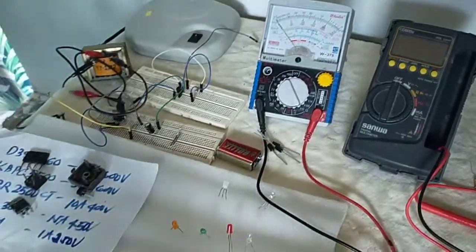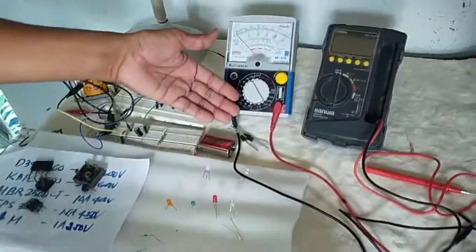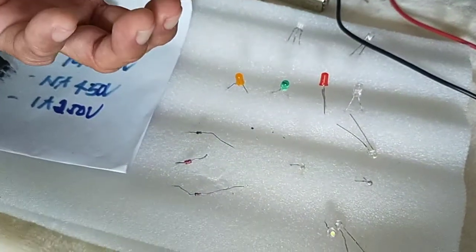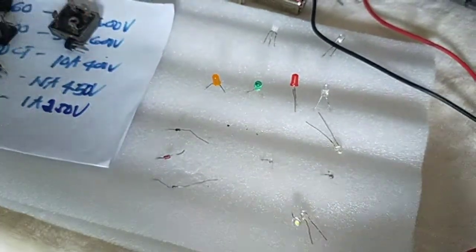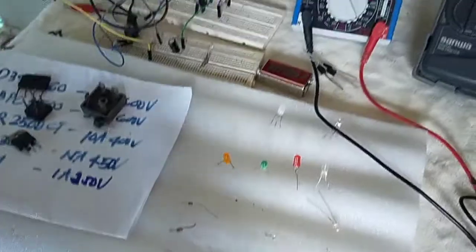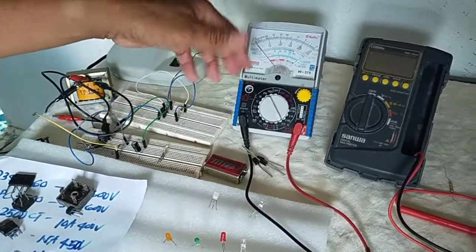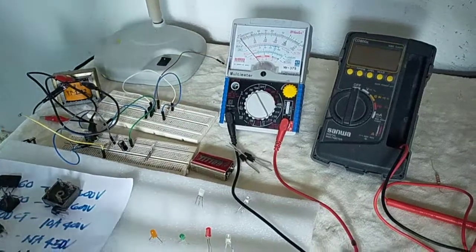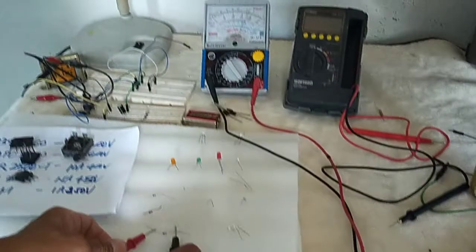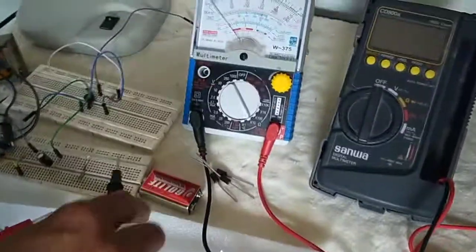Okay. How about these Zener diodes? The same with rectifier diodes, a Zener diode may also be damaged. There are 3 kinds of troubles also: leaky, open, short. Okay, we have here. We will use times 10 again. Do not use times 1, as it may cause damage to these semiconductor devices. Okay. We have here. Deflect. That is forward bias. This is forward bias.